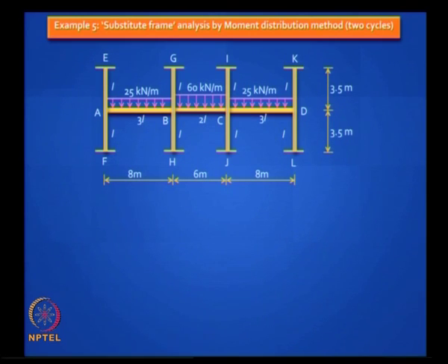slope deflection method. Now again I want to go back historically. This is how they did multi-storied frames in the olden days. I mean, it's too much to analyze the full frame. So we have this concept of substitute frame. You take any one floor and you assume that there is not much interaction between one floor and the next floor, and you can prove this using Mueller-Breslau's principle, and as long as there is no sway in the frame, you can isolate one frame and assume the columns to be fixed at the top and bottom.